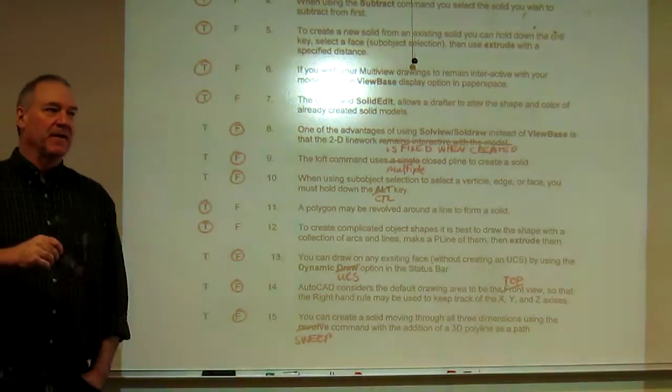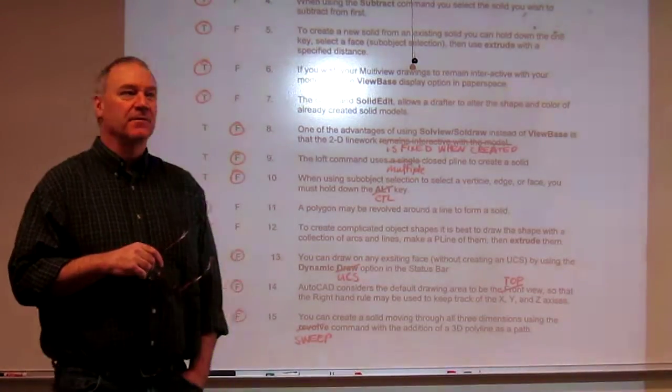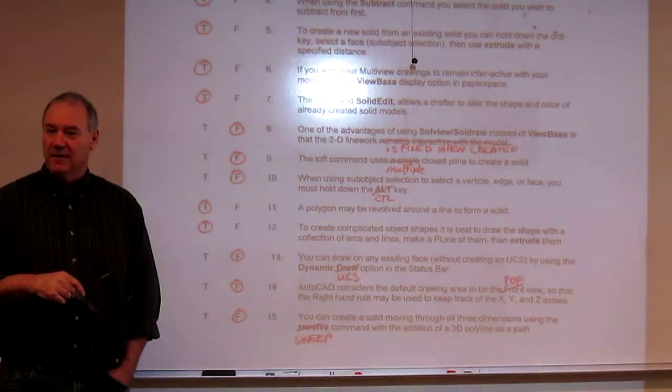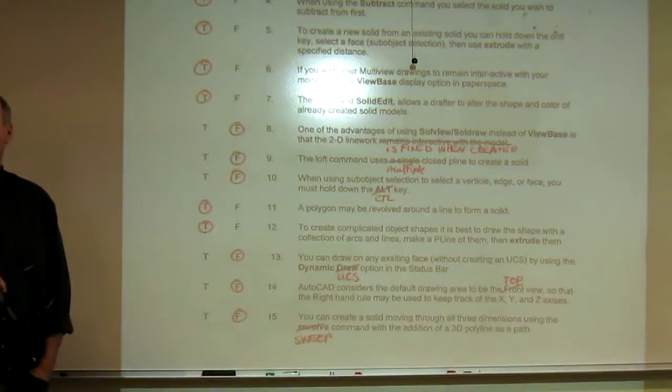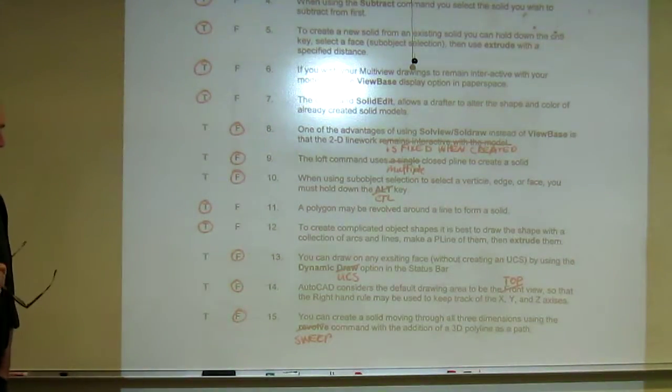Even if you use the polygon command, right, that does a hexagon or something, it's a P-line. Therefore, you can use it. A rectangle is a polygon. Those are all P-line based drawing objects. So why is its definition of polygon closed? Yeah. It's a closed shape.